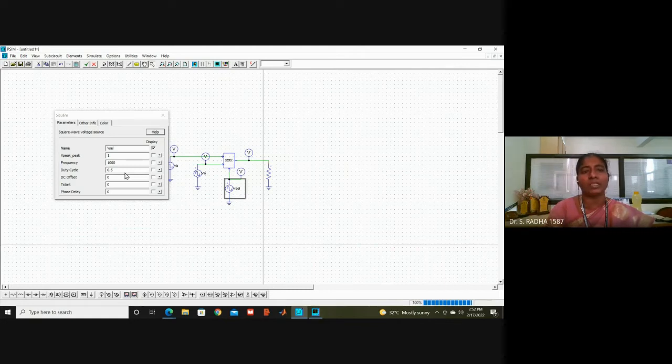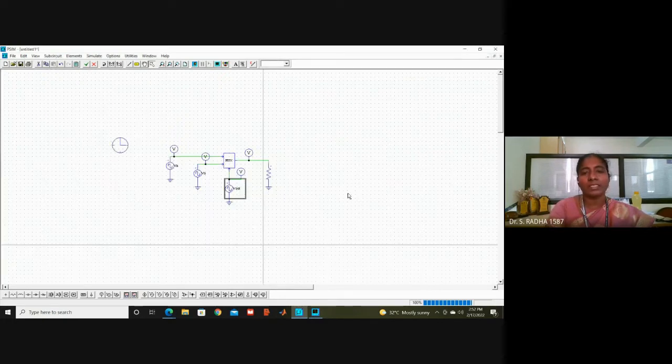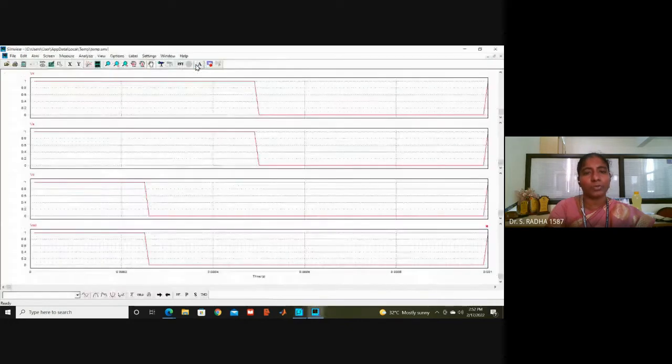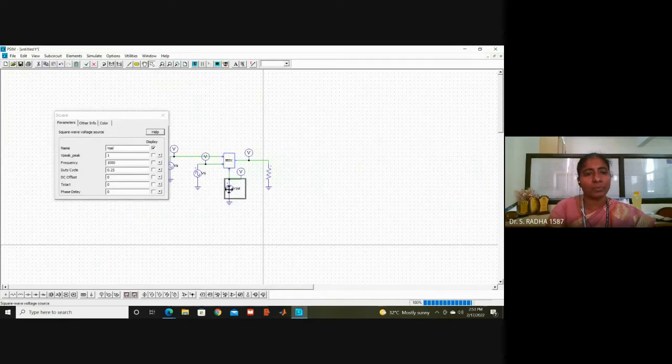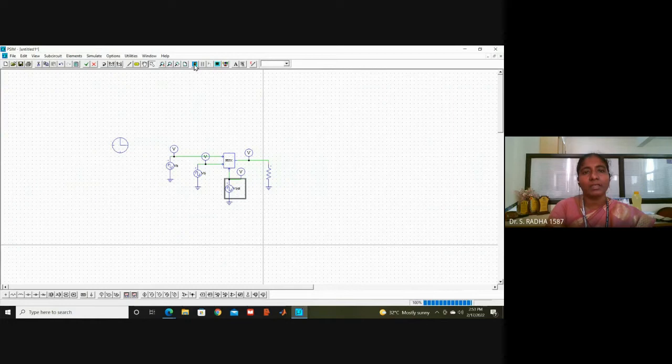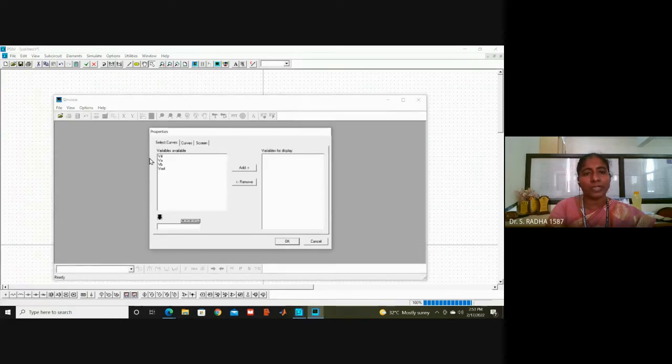You can check putting the duty cycle 0.25 also, you can get more clarity. Duty cycle of V select can be anything of VA or VB. You can put duty cycle for V select same as either VA or VB. Now I have changed it to 0.25. Waveform is already there. You can see here instead of 0.5, I changed selection line duty cycle as 0.25. Now what happens? 2 times it will come,